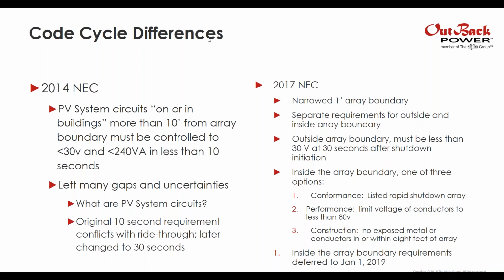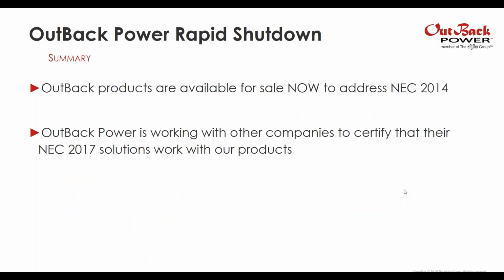But in parallel, what we're doing on hitting that performance requirement and limiting voltage of conductors to less than 80 volts after initiation of rapid shutdown is we're working with a variety of other companies to certify that their NEC 2017 solution works with our products.